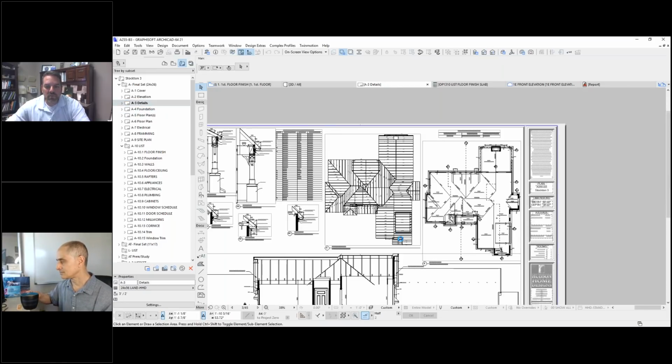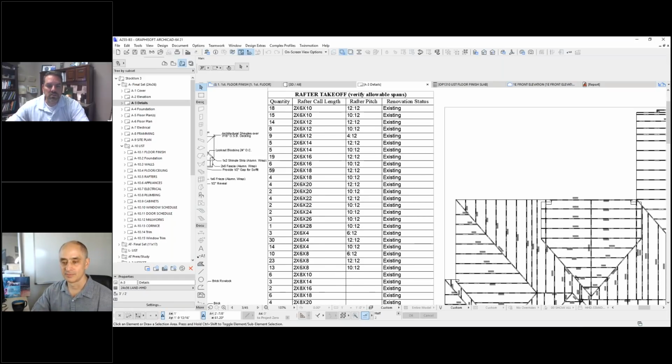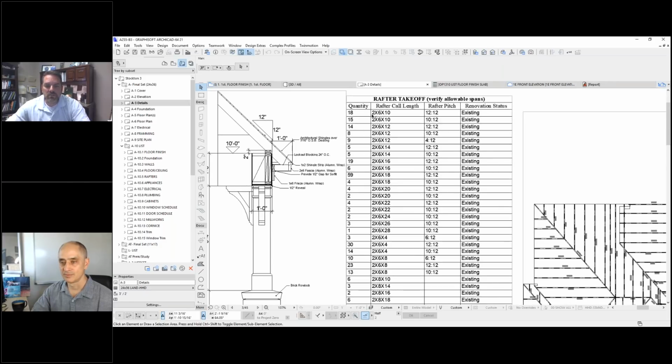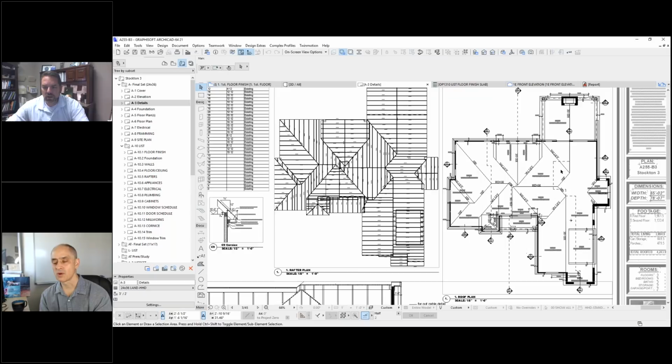And then we'll do maybe a separate detail sheet showing a cut list and the rafter takeoff. We can get into that, showing the rafter cut list as you can see on the rafter takeoff. We break it down by the nominal length, so the system's smart with the framers out there being able to pull from the right stock. It creates less waste versus just having a total number. They'll know that the 16 foot, they need 19 of those. Then again, on our roof.